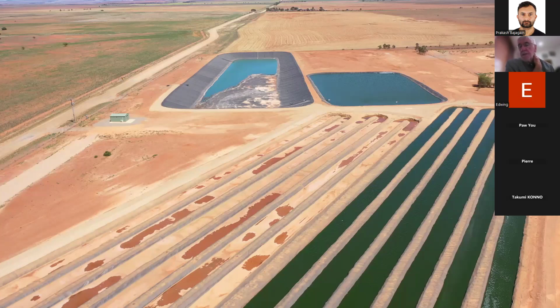And the question is, how do we persuade engineers, who are used to pouring large concrete structures and intensive aeration systems using lots of energy, how do we get them to start thinking about nature-based systems for wastewater treatment? I think competing technology would be wetlands. They seem more comfortable with adoption of wetlands for wastewater treatment, but there are certainly these algal systems. They offer smaller area requirements, greater efficiency, and an effluent that meets discharge guidelines.